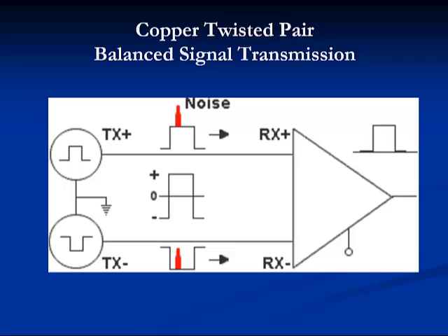When the two conductors are perfectly symmetrical, everything flows smoothly. However, minute changes in the diameter of the copper, the thickness of the insulating layer, or the centering of the conductor within that insulation cause disturbances in the electrical field called unbalances. Electrical unbalance means noise.